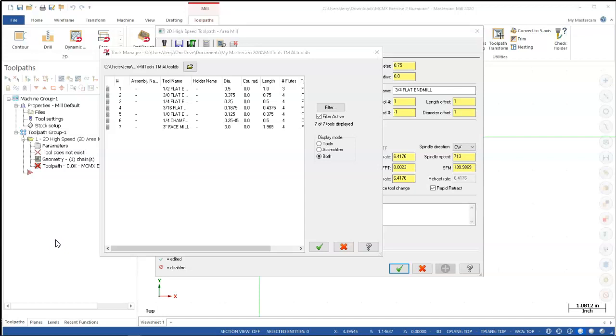But if I set up for an aluminum run and I have 4 different part numbers, but I know they're going to use the same grouping of tools, then I want this list that I can go back to, and I would just set it as the default. I'm going to program for those groups and just keep using the same list. So one of the things we need to do is get out in front of the machines and look at the different touch-off strategies that make that happen.